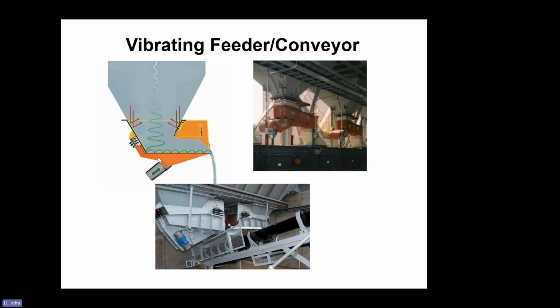So the materials vibrate here and discharge here with a small angle here. And usually this opening height is critical. If the opening is too big, it will flood here. If too small, it will be stuck here, cannot load out, or have some dead materials here. So it's critical to design this vibrating feeder with the right opening, angle and height.